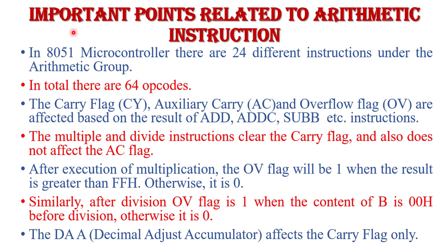Now some other important points related to arithmetic instructions that we should remember. First, in the 8051 microcontroller there are 24 different instructions under the arithmetic group, with a total of 64 opcodes. Whenever we perform any arithmetic instruction like addition, addition with carry, subtraction, or subtraction with borrow, the flag bits of the PSW flag register are affected based on the result of these instructions.